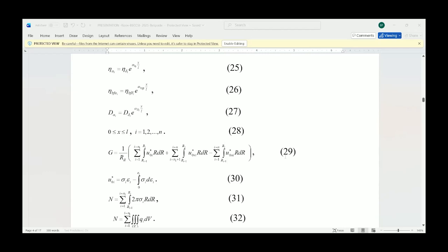The specific complementary strain energies are extracted from the stresses and strains in the cross sections of the layers of the external crack arm behind the crack front and in the cross sections of the layers of the rod ahead of the crack front by applying formulas analogical to that in equation number 30.